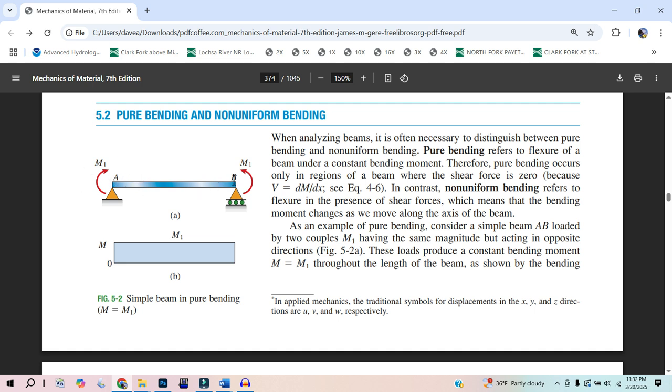So if you had a flexible ruler, applying a moment at point A and B would be like taking two fingers on each hand and applying an upward and downward force, basically a moment. A moment is always like two opposing forces separated by a distance. And I think I kind of got the directions wrong. So if this moment goes this way, I'm going to have a downward force right here and then an upward force right there. That's going to cause this type of rotation. Cool. And then the same over here.